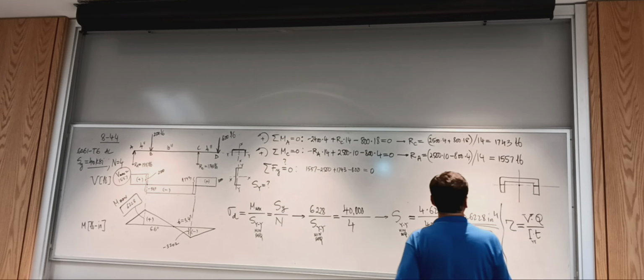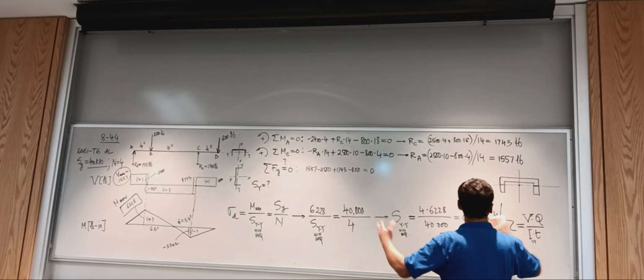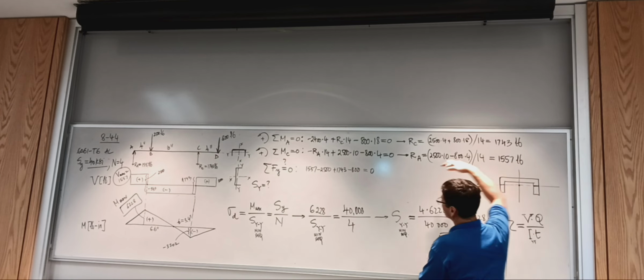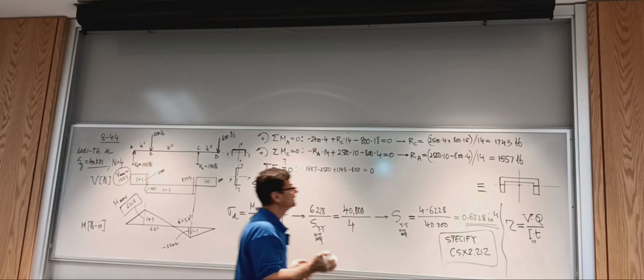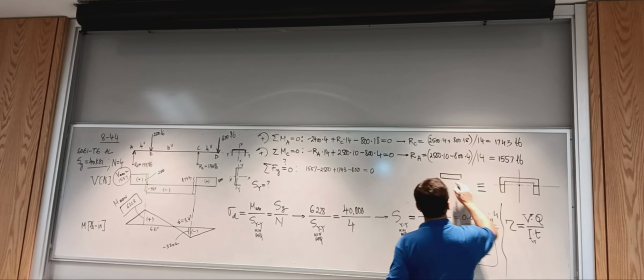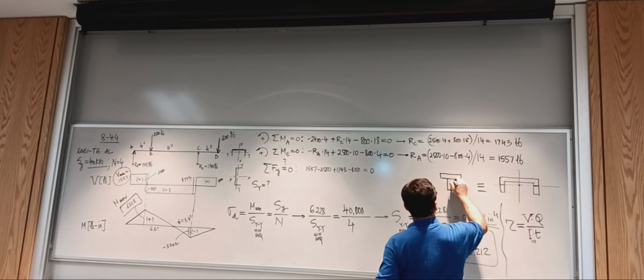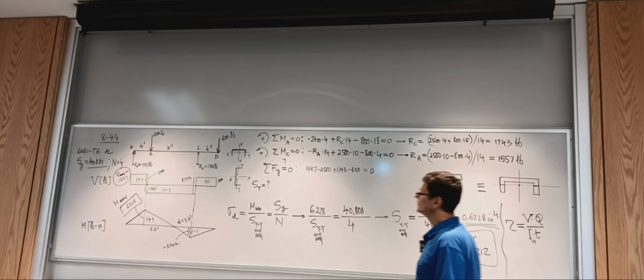Well, in terms of shearing behavior, I started saying that if it's a channel like vertical, it's equivalent with an I-beam. If I take this, I just move the flanges to the middle, and it's the same thing. It's just a matter of how you distribute the loads.